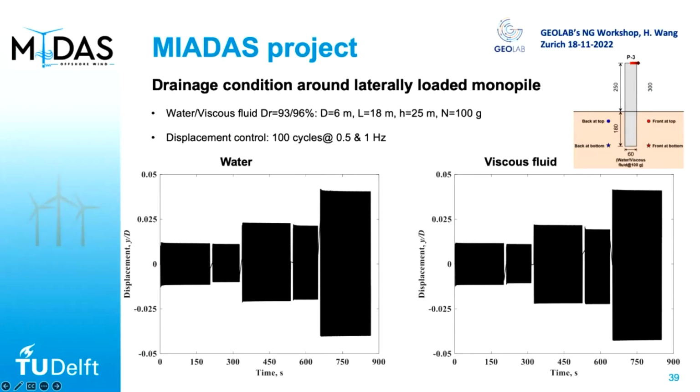We put the pore pressure sensor around one pile diameter away, and as you can imagine, when you're close to the pile, the soil deforms more, so there may be more pore pressure response. But it's the centrifuge test; we didn't have time at that time to instrument the optical fiber. But we are going to do some numerical simulation to quantify how much this will really affect the pore pressure response. Mike?